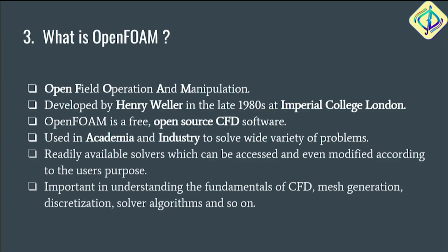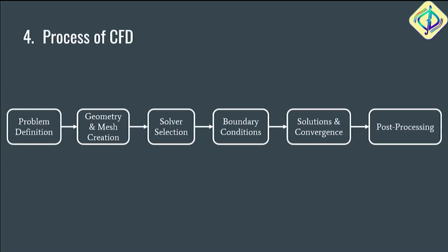So OpenFOAM is good that way because it helps you understand what boundary conditions you're putting. You're not just simply clicking a button and not knowing what it does. In OpenFOAM, the person who's using that software has to know inside out what exactly they're doing. Otherwise, you will end up with just, as Professor Chandan would say, colorful fluid dynamics. Yeah. So the process of CFD.